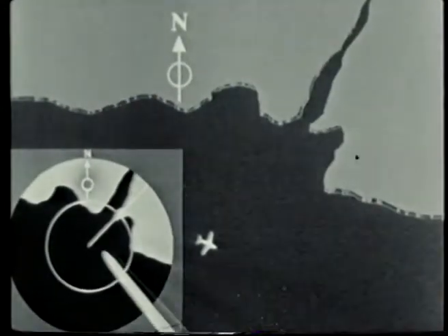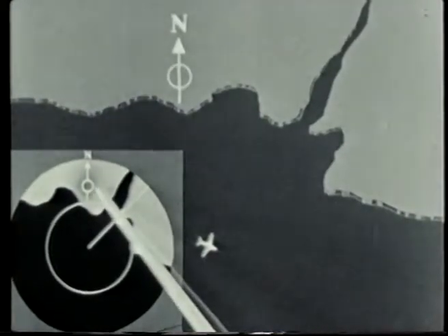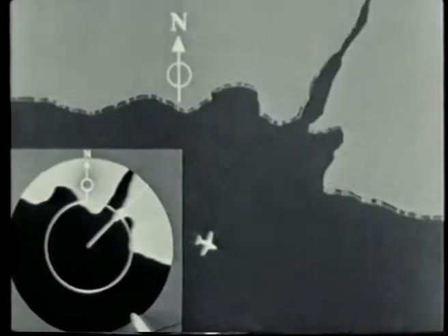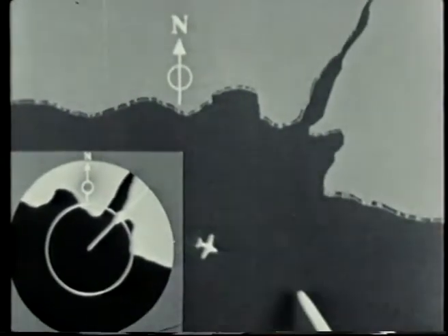Although the markers behave as polar coordinates, range and bearing, they are always derived from the north-south and east-west components, which are available as voltages on the marker potentiometers. The radar picture and the bearing line are both referenced to true north. That is, north is made to be at the top of the display irrespective of the heading of the aircraft.